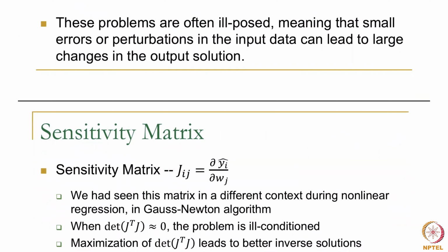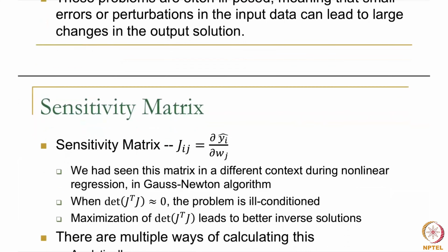What this means is if I change the thermocouple location a little bit or the thermocouple measurement a little bit, in case it's an ill-posed problem. The problems that we did, again, in this example as toy problems were not particularly ill-posed, but it gets ill-posed as the number of data points actually increases, or the number of parameters to be determined increases. So whether the problem is ill-posed or not can actually be determined using sensitivity analysis.